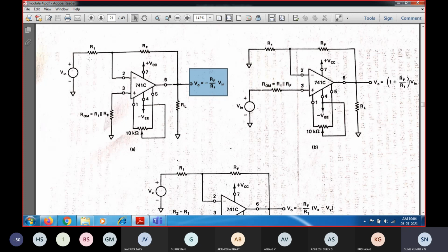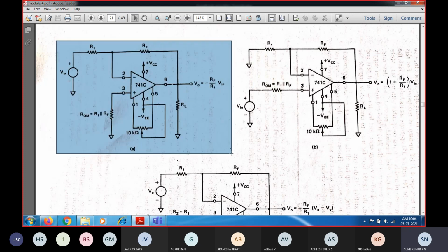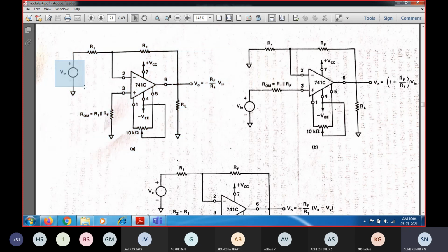In this, we are going to see the manufacturer recommended method for 741. He has provided an offset nulling terminal, so this configuration is called an inverting configuration with offset nulling circuitry provided over here. And why is it called inverting? Because you are going to provide the input signal at the inverting terminal, so the configuration of the operational amplifier is called an inverting amplifier.